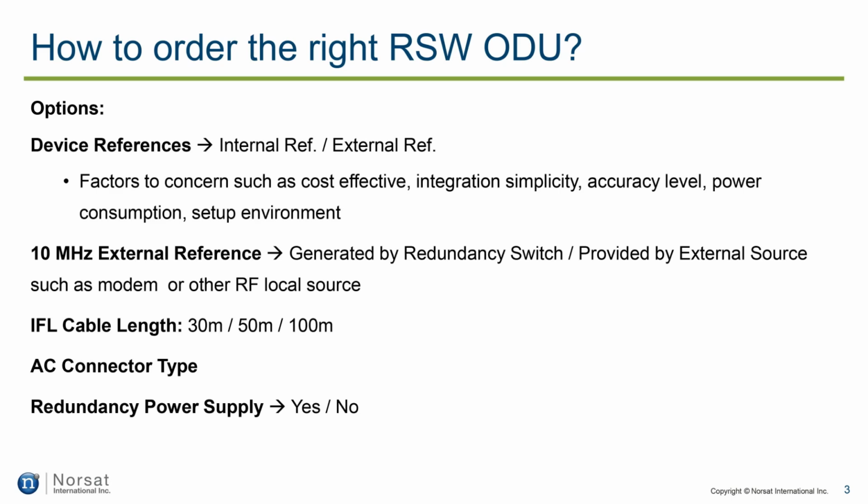If you need a longer cable to connect to the controller box, you also need to consider cable loss. Cable length is limited to 100 meters due to Ethernet signal restriction, unless extra accessories such as a PoE extender are used to amplify the signal to compensate for the cable loss. We'll cover this topic of IFL cable in more detail in the next 2 slides.